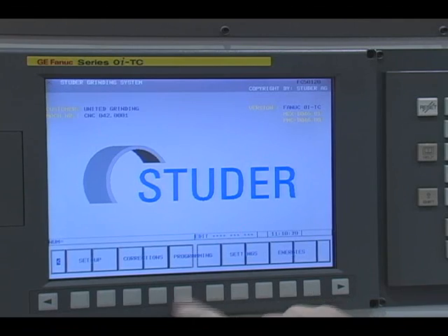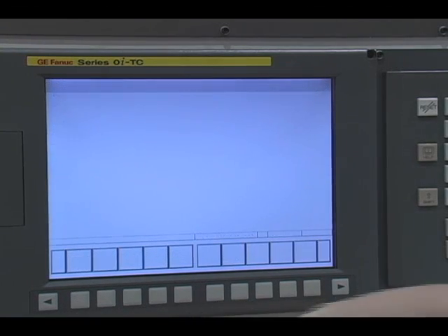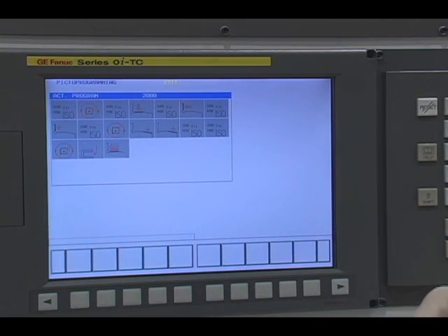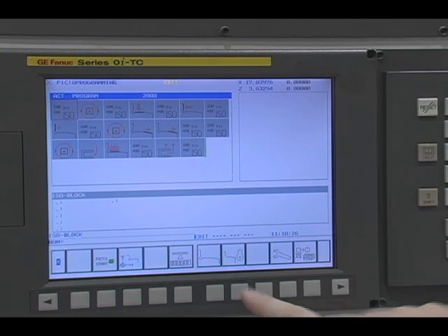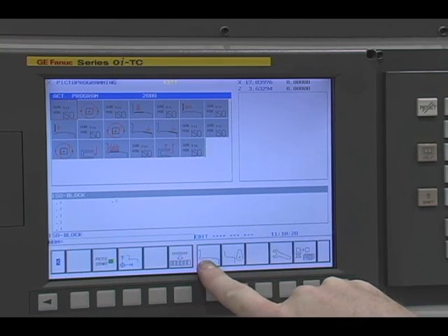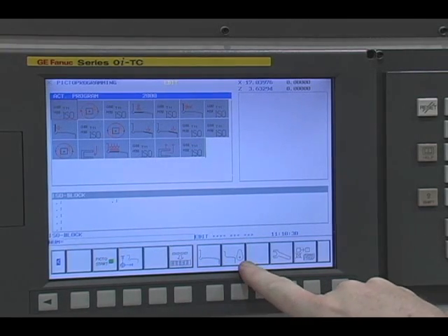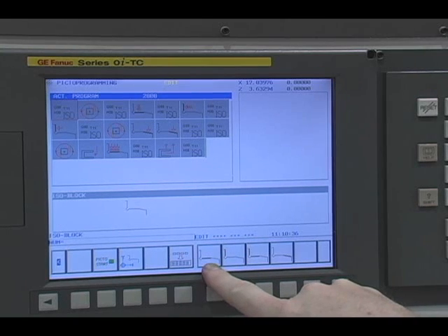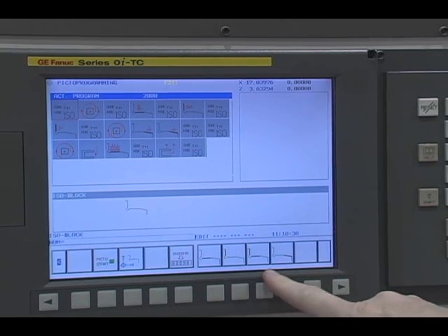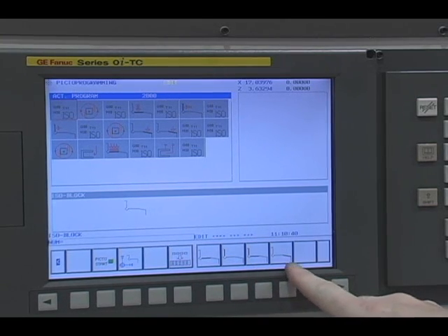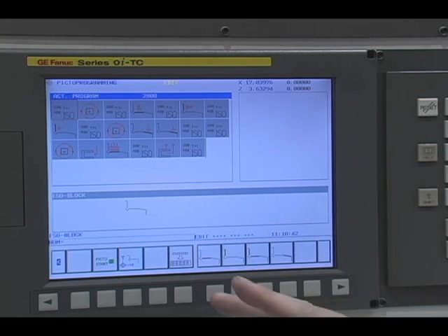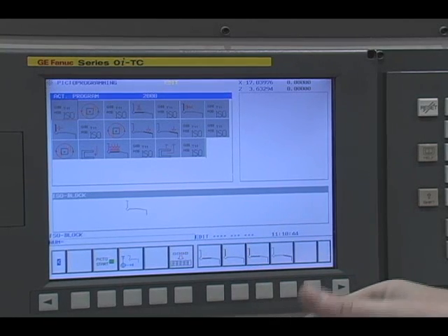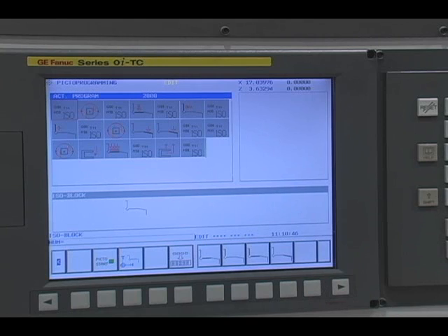I made a part program using pictogramming. What pictogramming is, students put together all your basic geometries as far as diameter grinding, contour grinding, and non-round shapes and forms. From the diameter grind, we have options for a straight diameter grind, a shoulder grind, an angular plunge grind, and the taper grind. You look at your drawings, you look at the features on your drawings, and you select the geometry direct from there.